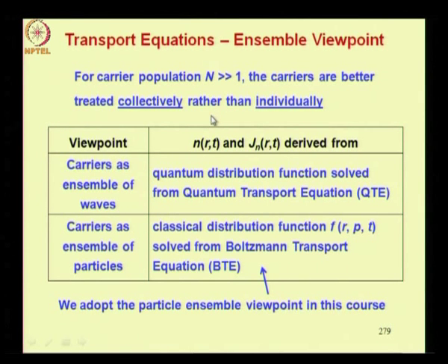Now coming to transport equations, the ensemble viewpoint. When the carrier population is rather large, then we treat the carriers collectively rather than individually. You have two viewpoints, either regard the electrons as ensemble of waves or ensemble of particles. If you regard as ensemble of waves, then use the quantum transport equation to solve for the quantum distribution function, and from that you get the carrier concentration and current density. Now if the carriers are regarded as ensemble of particles, then you use the Boltzmann transport equation to solve for the distribution function f, and this is the approach that we have used in our course.